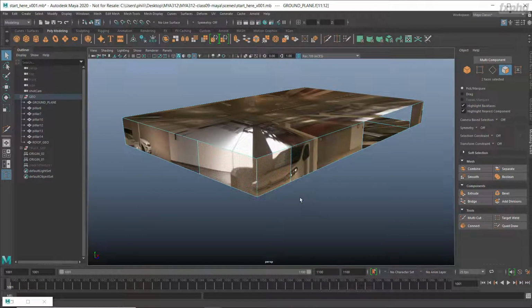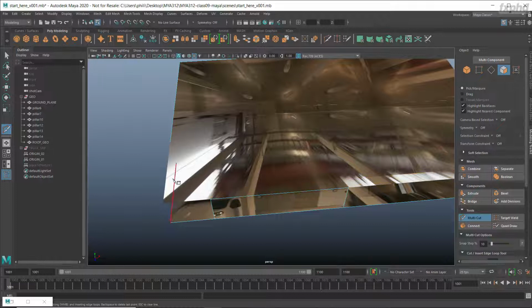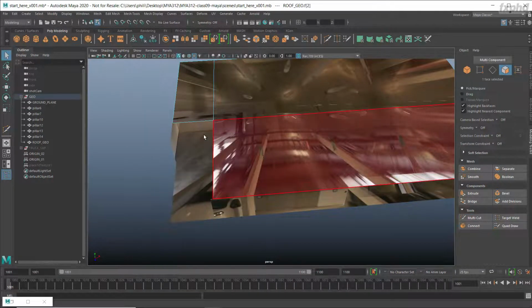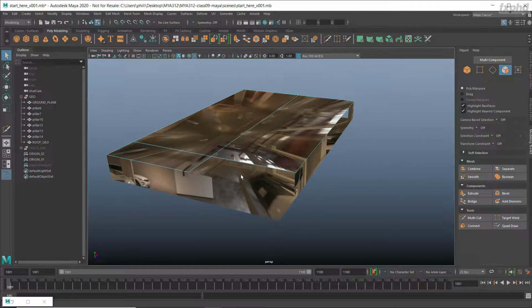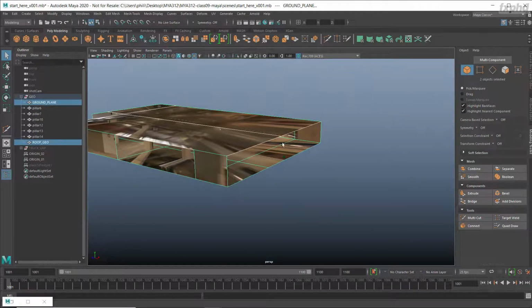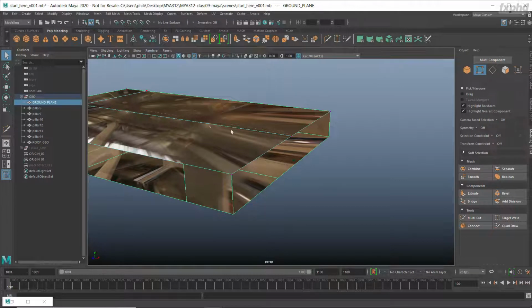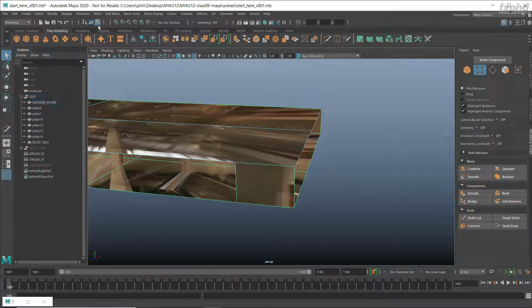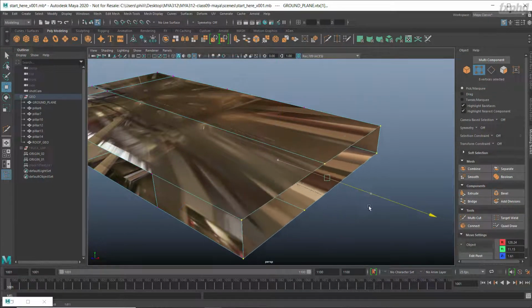Okay, now I'm just going to cut away these two walls. Let's remove a section of the roof as well, because this is actually a ramp coming into the car park. Okay, so this is going to allow us to have some light spilling in from each side. Okay, so now I'm going to grab these two objects, switch over to Vertex, select by component, grab this end section, and I'm just going to give us a little bit more room back here.